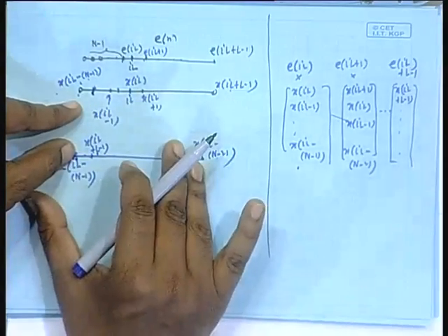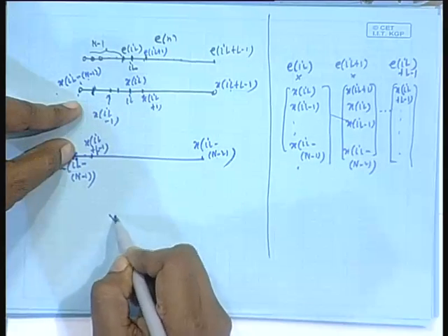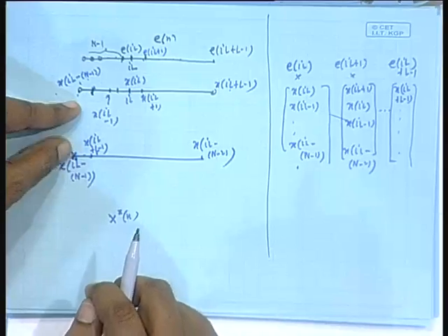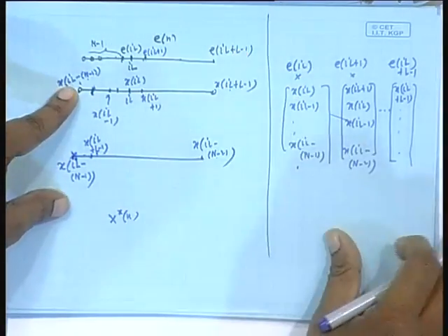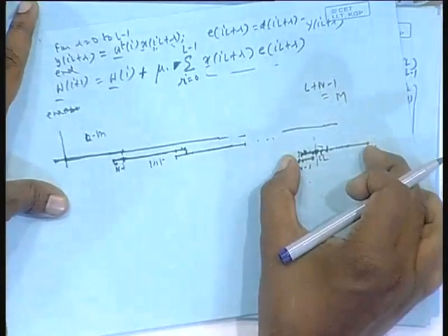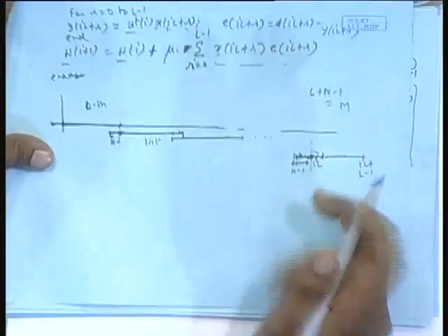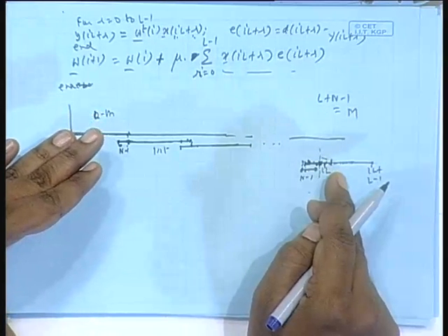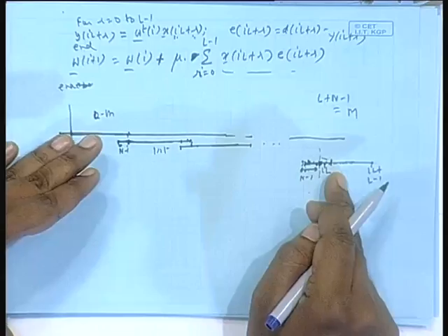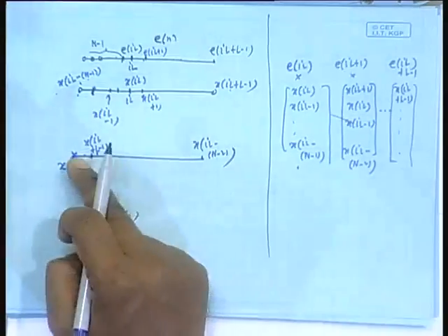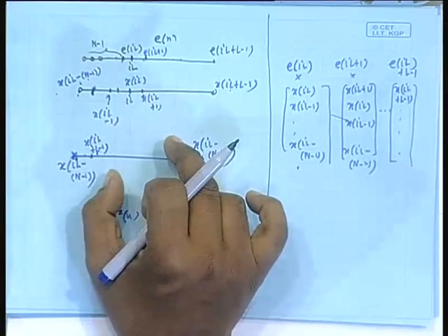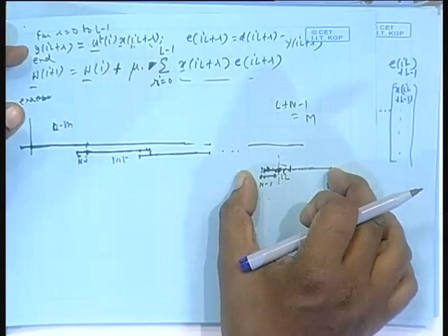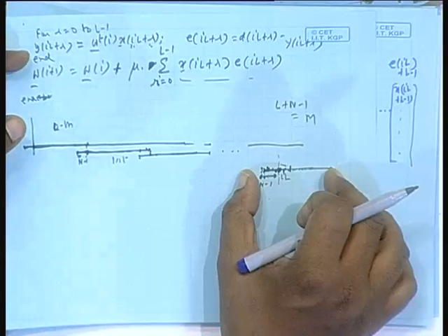Then if I take a DFT, I will get x star k, where x k is the DFT of what? This basic vector, simple block, these blocks. Take a block, and where do I need this DFT? In the filtering part, overlap and save method. Same DFT, I do not have to recompute the DFT of this reordered vector. I computed the DFT only once here. That is how the computational gains come. Otherwise, one more DFT would have been required, isn't it?